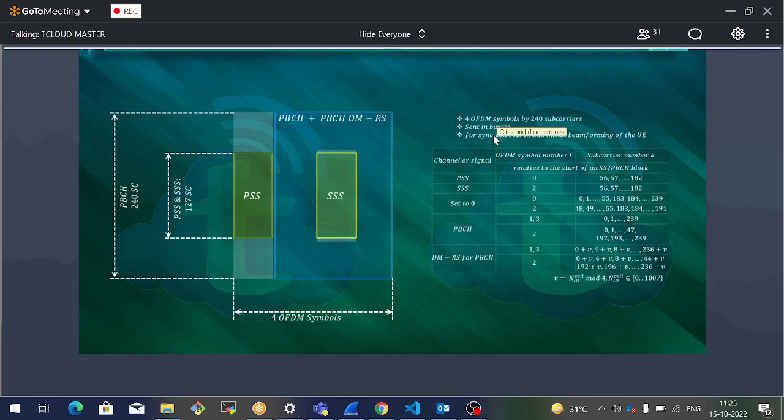Mobile can decode all these symbols and find out the ones and zeros present inside by demodulating the symbols easily, by finding out what are the I plus JQ symbols present inside. But what channel those symbols belong to, mobile should know. But there is help available by fixing these rules and regulations. So mobile knows the position of these PBCH symbols in the SSB block it has detected. So what does the mobile do? Next, go and deal with the PBCH channel.